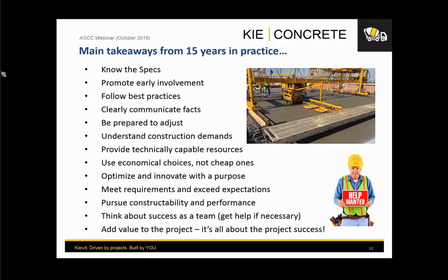There are several things that I think are very important. Communicate the facts. There's no reason to hide the facts, right? You deal with them, you present them, you look for solutions. Be prepared to adjust and understand construction demands. We as builders need to understand what construction demand means to the operation, and what it means to the materials we're going to select, right? Use technically capable resources, and use economical choices, not cheap ones. I went through that already. The economics of mix designs is not selecting the cheapest one, the lowest cost. Low cost of operations means something more than just the unit price of the mix.